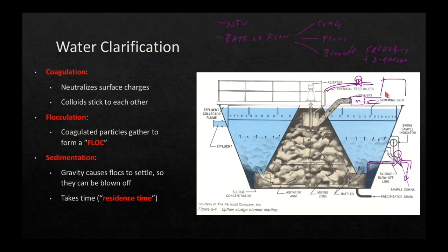But really, what we have is a controller. We've got this brain here. Okay, there's our controller brain. And so based upon the influent flow and the water lab testing, we have an output signal that controls how much chemical is being fed and also controls the rate and duration of blow off. So all we're going to be doing is maybe just fine tuning things, or maybe doing the occasional manual blow and stuff like that.